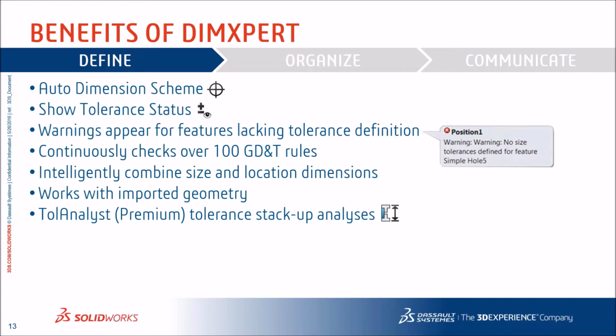The Show Tolerance Status feature highlights each of the faces that have been fully defined by one of the DimExpert dimensions. So you know your job is done defining the manufacturing information once all the faces on the model are highlighted. That is an invaluable feature of DimExpert. Not only that, think about GD&T. There are so many ways that people interpret and implement it, where it does have some standards and there is a proper way to implement GD&T.